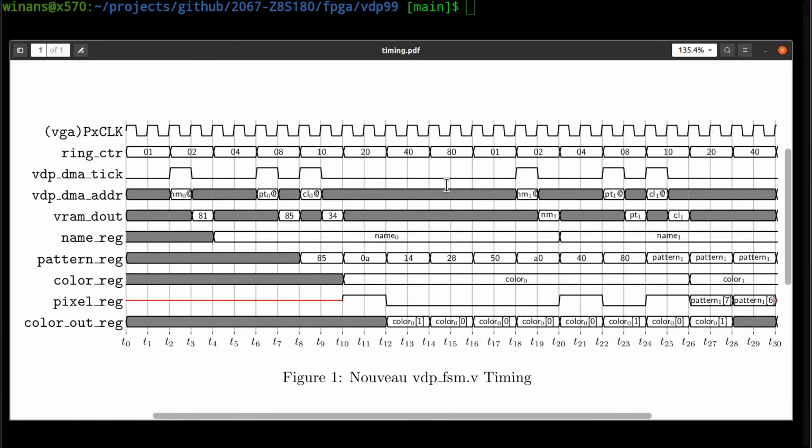And as I mentioned last time, the only way the CPU can read the VRAM memory is by using this automatic counter that advances after every time the CPU reads a value. And the VRAM logic has this look-ahead that it can use to pre-read the next value in case the CPU comes back and wants to consume it, right?